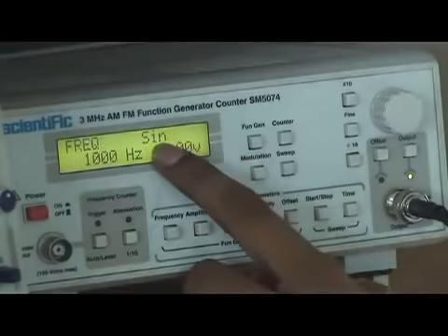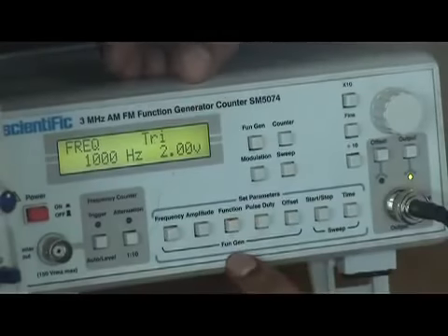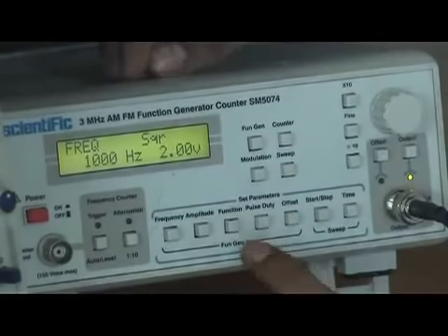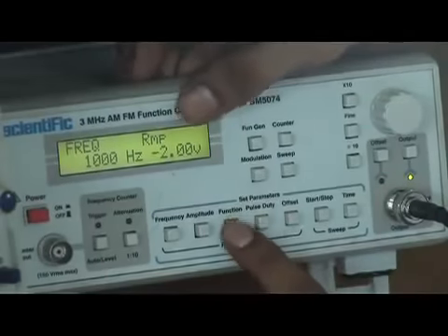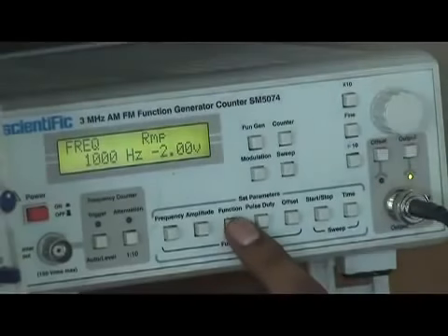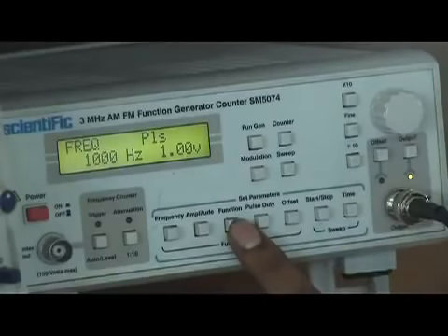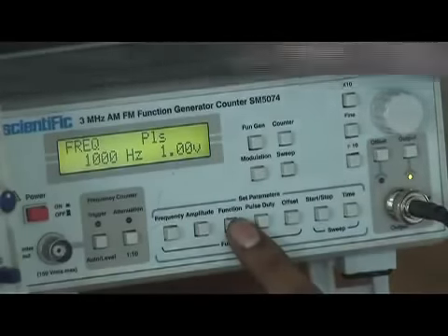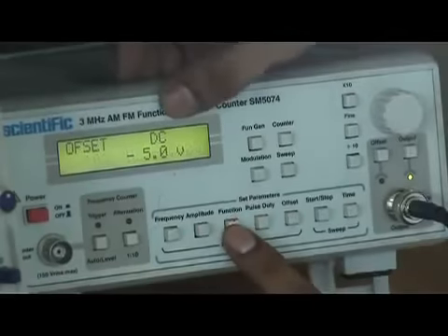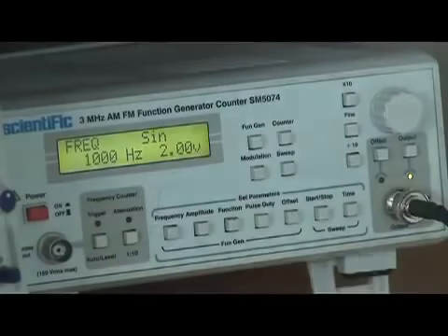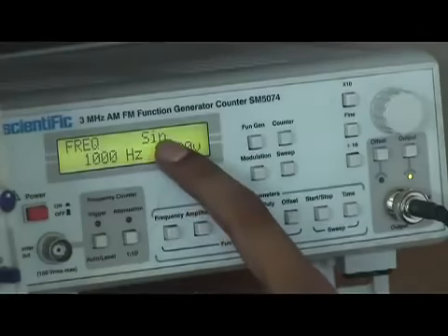Now what is the function? My function is sinusoidal. You can change the function from sinusoidal to various functions like triangular. If you press it again, square. If you press it again, this is again a square. Ramp, it's 2 volt. Ramp minus 2 volt means a negative ramp. This is pulse 1 volt, because when we say pulse, it denotes only from reference to the upper level, or reference to the below level. When I press it again, it says a pulse of minus 1 volt, means below. Then a DC voltage, then again back to the sinusoid. So right now we have set it for a frequency of 1000 Hertz, an amplitude of 2 volts, and a function of sinusoidal wave.